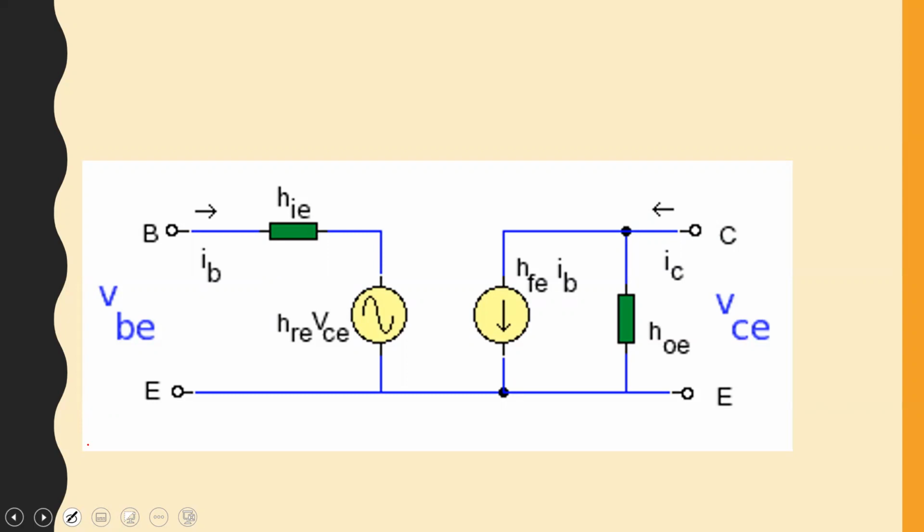So let me bring you back now to what we said earlier. We started at H11, yes? And we said that H11 was the input impedance. Okay? Short circuit input impedance. The I in that parameter represents input. We then also spoke about H22.